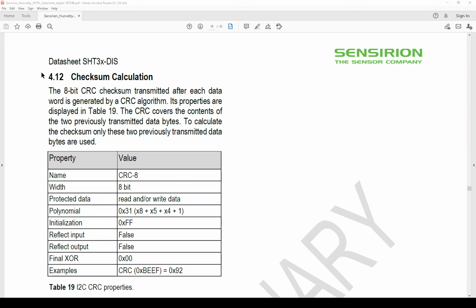So the CRC calculation is based on a lot of theory, and it's designed to detect as many error cases as possible. I won't go into that, but you might want to do some more reading on it. Now, fortunately, it's easy to find C code to compute CRCs on the web. The table sort of contains input parameters for that code, and we'll look at the CRC calculation code later in this lesson.